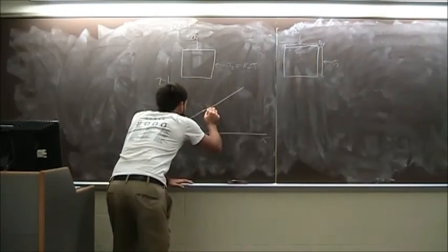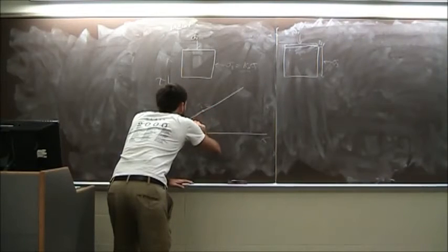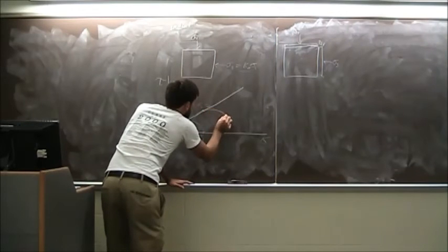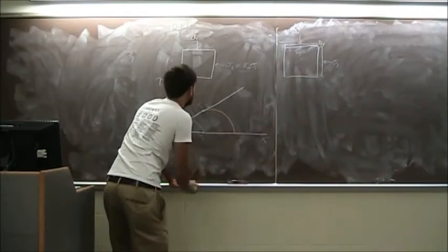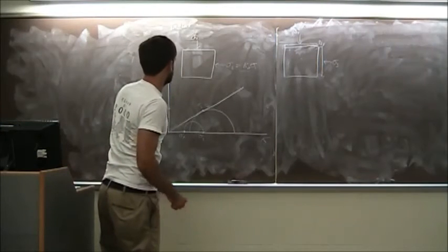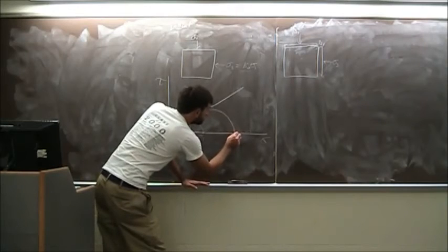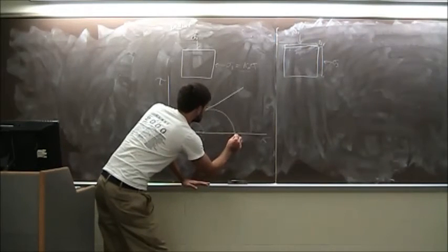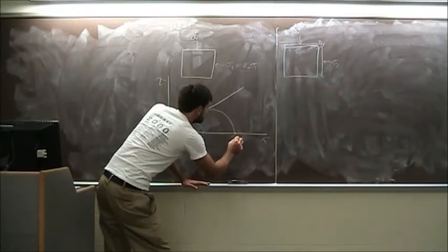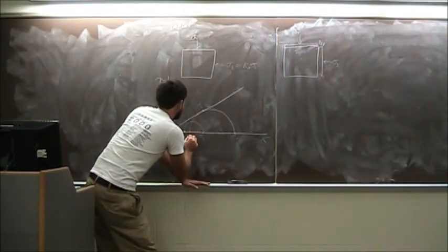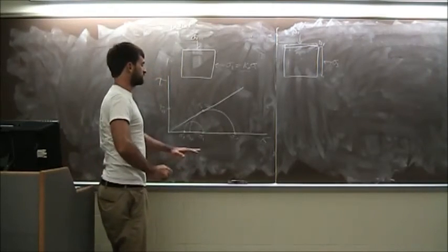So I'm going to try my best to have this look good. Okay, that's not too bad. All right, so now we can graphically figure what these stresses are, but for our purposes, this is sigma. This is now sigma 1 failure, and this is sigma 3 failure. And that's your principal stresses of failure.